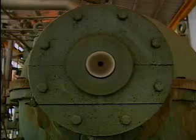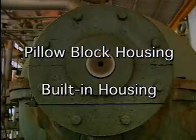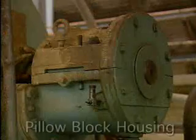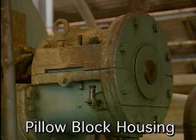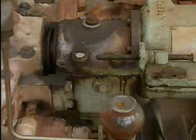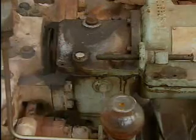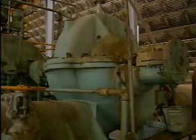Bearing housings are divided into two types: pillow block housings and built-in housings. Pillow block housings are located outside the machine casing and are separate from it. In some cases, the pillow block housing holds the end of the shaft. In others, the shaft passes through the housing. Pillow block housings can be either solid or split, and they come apart in different ways.